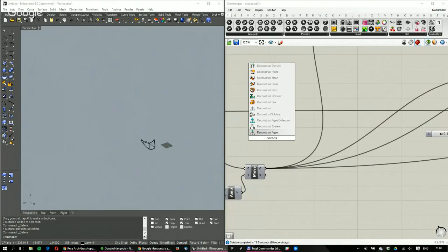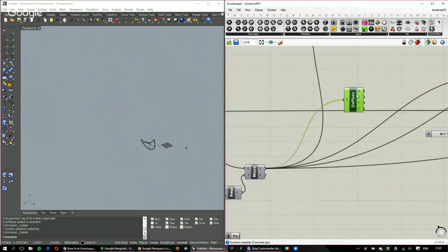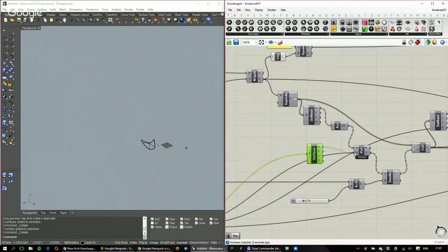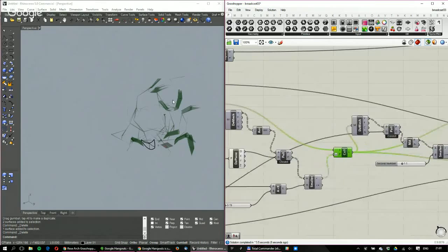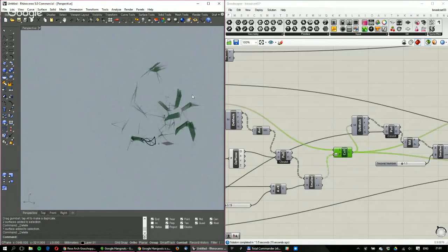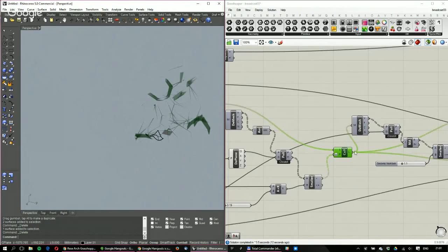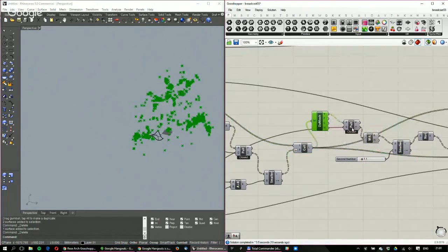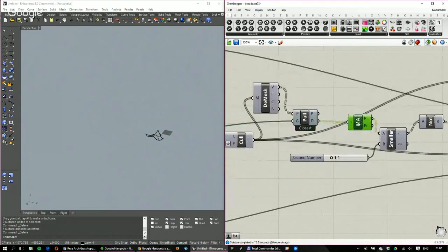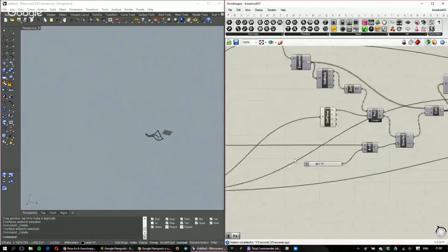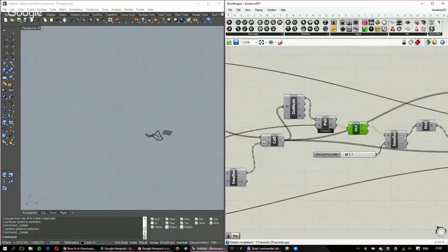Now I will deconstruct the plane. And instead of pulling it to the plane itself, I will pull it only to the origin. So now I will cull off everything that is too far from that growing point, and I will grow only the close geometry, which is, in this case, this one. So it's a sphere around that growing point. Then I deconstruct the mesh again, and I again pull all the points to the construction, to the cutting plane. What do I do then?